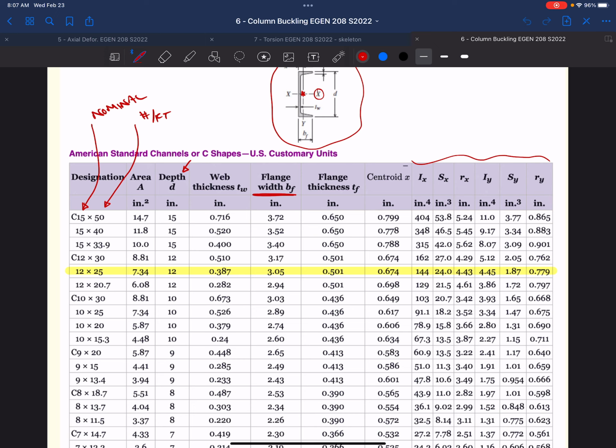And so we want to be mindful of not only the difference in mechanical properties, our moment of inertia, I, plays a big role, okay? E plays a big role. Usually, though, the column is all the same material, so E should be the same in both directions. But the I changes. And then on top of that, in the real world and in the homework I'm going to give, we can have different restraint conditions in two directions, right?